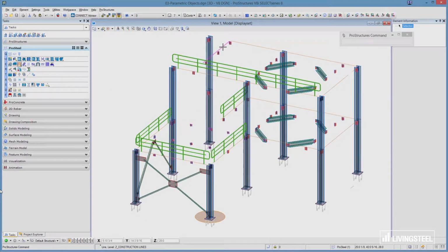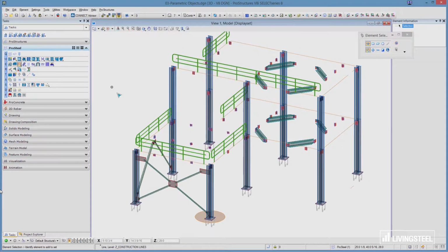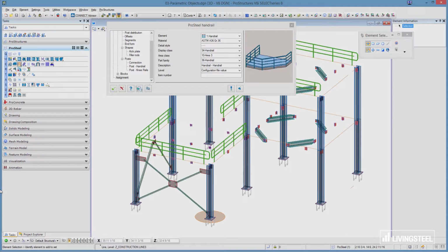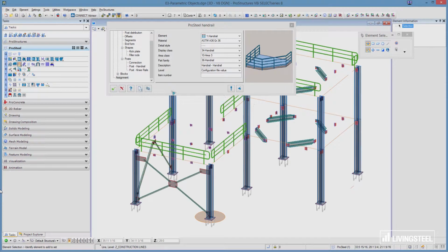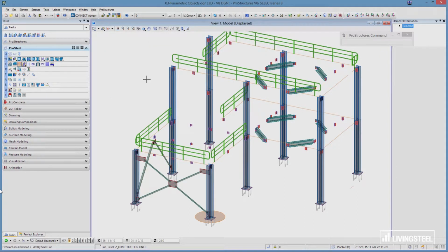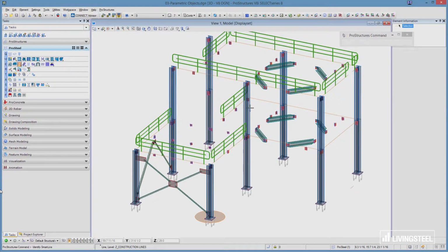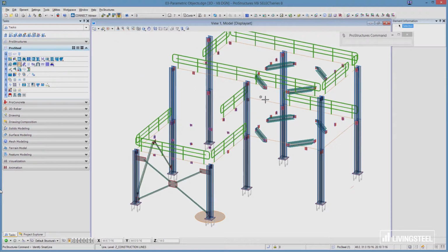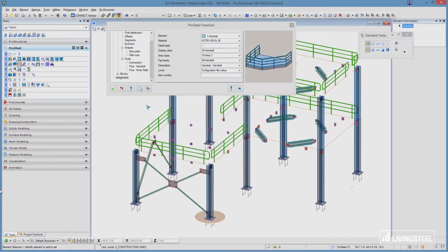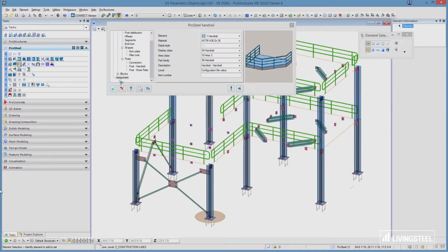Now, we don't have in this example handrails that turn corners, but the handrails can turn corners, as you can see in this image here. In my case, they are all individually set, but we could have handrails that turn corners if need be. Handrails can also go up and down staircases. You just need to trace your line at whatever angle is needed, and you will have the handrail with vertical posts going down a staircase. So as you can see, I'm just quickly finishing all the handrails here. I think I've got 2 more, and we'll have all the handrails built for this model.